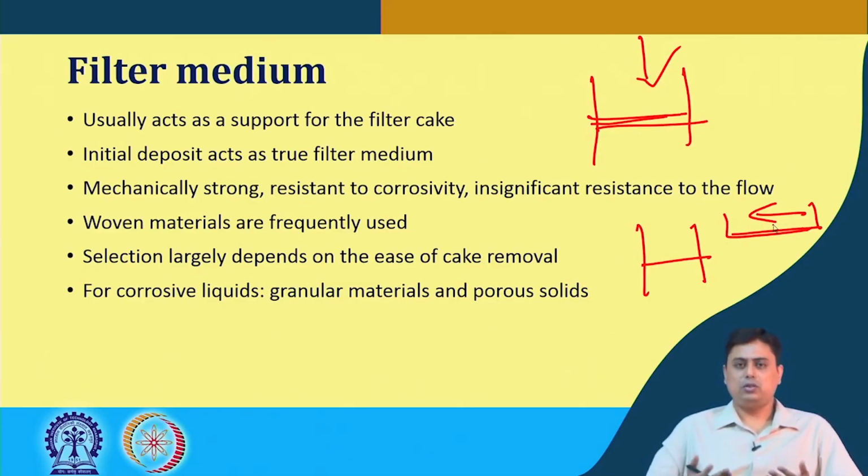We can process those solids and we can recover the solids. So, the choice of this filter media in such cases should be such that we can easily take out that cake and wash it.